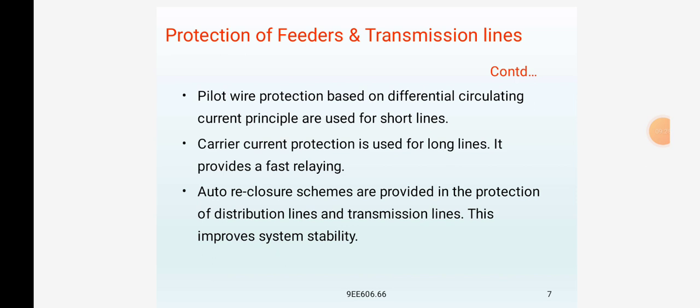If a fault occurs within the protected zone, the current entering the bus will no longer be equal to those leaving it. The difference of these currents will flow through the relay and cause the opening of the generator breakers and each of the line circuit breakers.